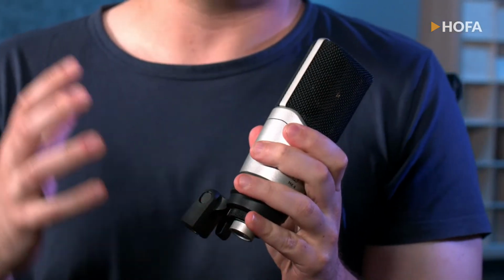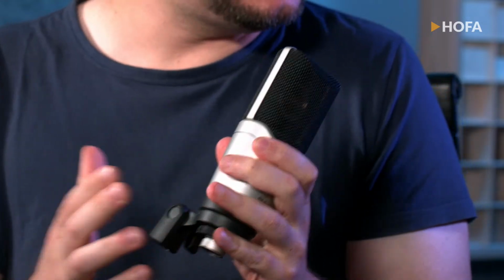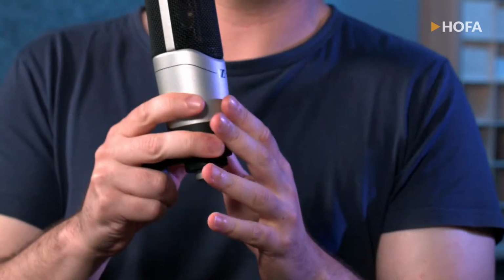Compared to that, the condenser world. We have a condenser microphone, which works a little bit differently because you need to feed it with 48 volts of phantom power to make it work. The conductors inside and the diaphragm will move, but that has to do with electricity and signal flow, and I don't want to go into depth. That's a Sennheiser, German brand, MK4. Not that expensive, but really good sounding. You can use it for vocals, maybe acoustic guitar, also drum stereo overhead recordings.